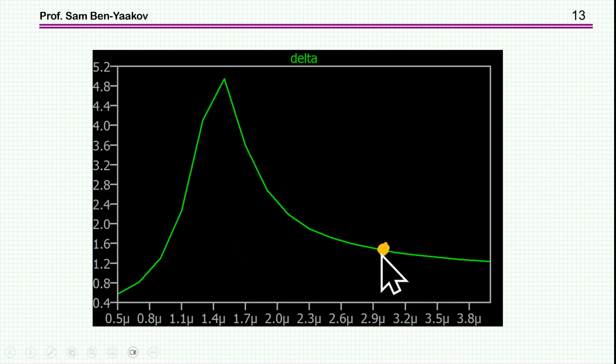We've been here because the capacitor was assumed to be 3 microfarad, but you see that at 1.4 microfarad, we have really a resonance here, and the peak-to-peak voltage across the ferrite would have been like 10 volts. That could be actually dangerous.